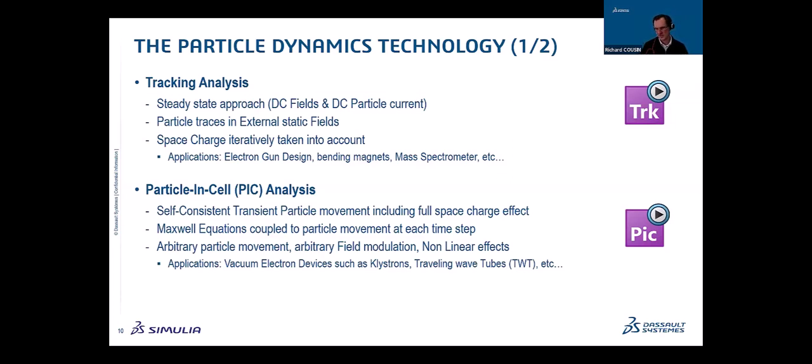which takes into account at the same time the coupling between Maxwell's equations and the equations of movement for the particles. And at each time step, we compute Maxwell's equations. Then we modify the equation of movement for the particles, and then this is re-injected at the next time step into Maxwell's equations in order to drive and to perform the nonlinear effects that you have step by step in the simulation. The market addressed here is related to vacuum electron devices such as klystrons, traveling wave tubes, gyrotrons, and so on.